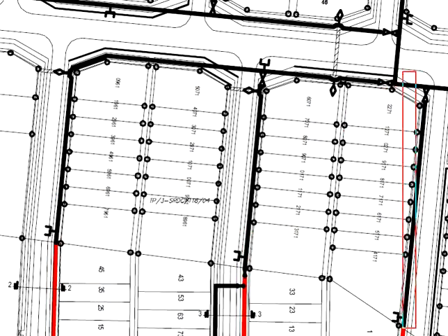One more thing about the layout of the water mains. Normally they are placed in front of the building units. Have you ever wondered, for two rows of buildings here, wouldn't it be more economical if you provide the mains at the back of the buildings? Instead of having two mains here servicing two rows of buildings, why not just provide one main here servicing both rows of buildings? There are two reasons for this.